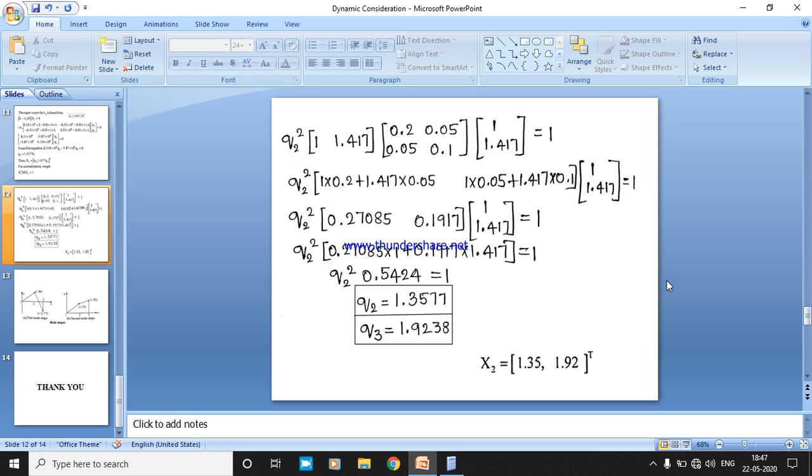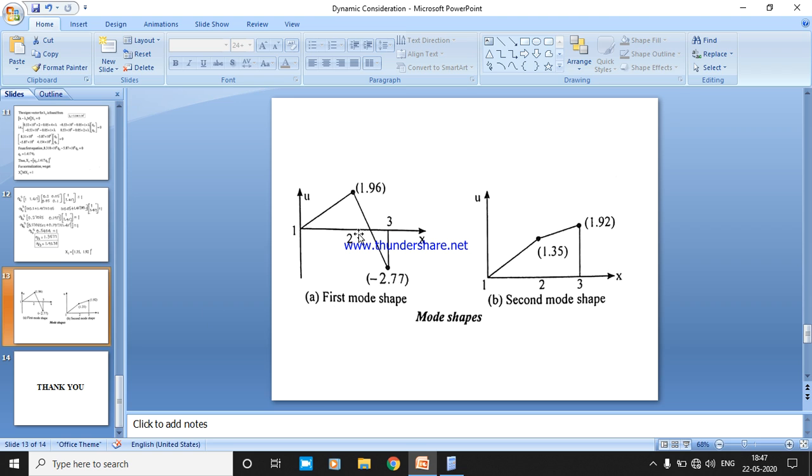So eigenvalues, I said, are found to know the natural frequency. Then using eigenvectors we can find the mode shapes. So here we have the eigenvector values. This is the first mode shape and second mode shape. So we can easily find what a mode shape is, how the shape is deforming. Based on this mode shape we can easily identify the failure analysis.